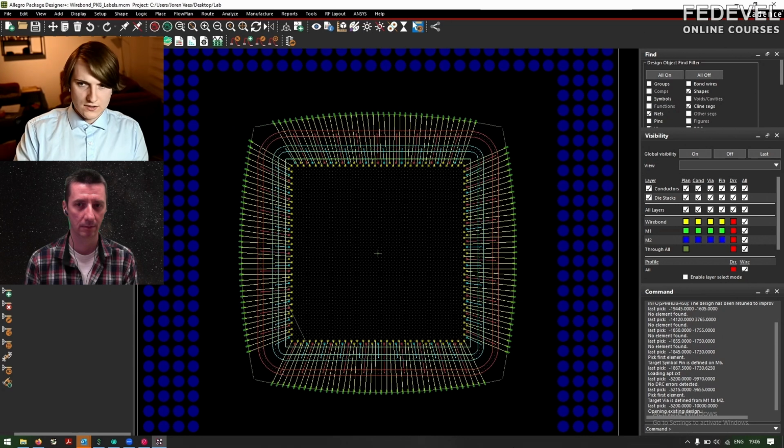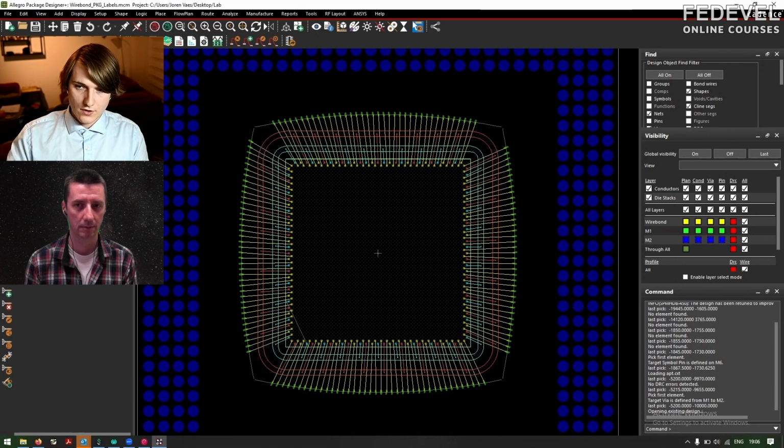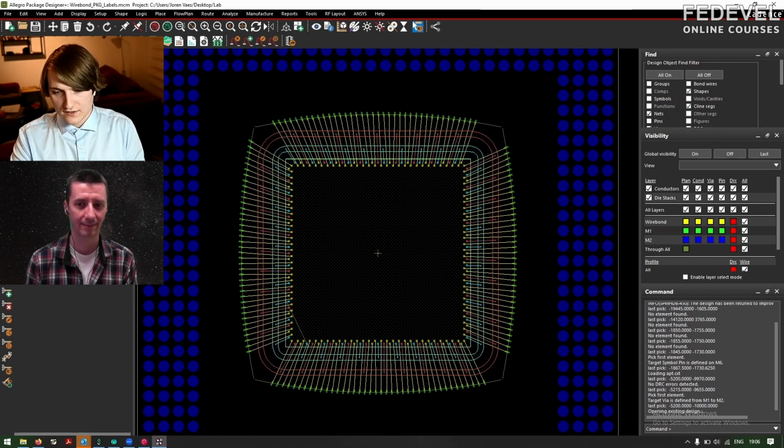And what you even see in industry is that they might not just do wiring, but you might have a CPU chiplet in a 7 nanometer FinFET or a 5 nanometer FinFET, and then for the substrate material you use an older technology, a 180 nanometer technology, and they do voltage regulators and power management, clock generation in the package substrate. And then it's placed in the same way. You have solder balls or copper pillars that you place on top, and then you have a packaged chip.